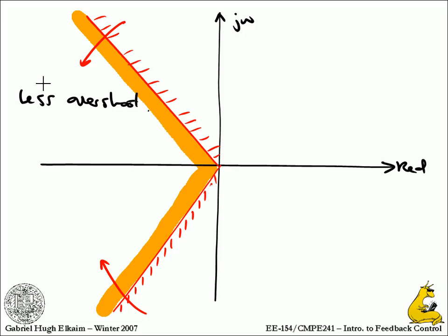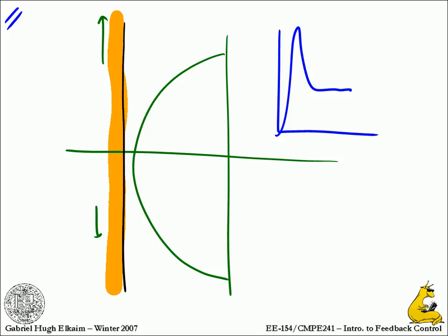What we also mentioned was that oftentimes one spec will drive the others. So there'll be one spec that, for instance, if you give me a settling time that is, in this particular design space, the settling time swamps the rise time specification. The settling time is more important, and therefore, by matching my settling time anywhere, I already meet my rise time spec. And sometimes it'll be like that, sometimes it won't. It'll be dependent on the problem itself.